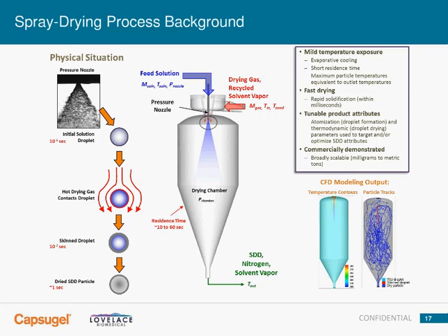This can be very important for things like biologics, where people might look at the high temperatures and think they can never survive that. The nice thing, though, is we have evaporative cooling at the surface, which shields the particles from the high temperatures of the process and the rapid solidification, hopefully in a high glass transition temperature matrix, to limit mobility of these particles as they're swirling throughout the chamber.